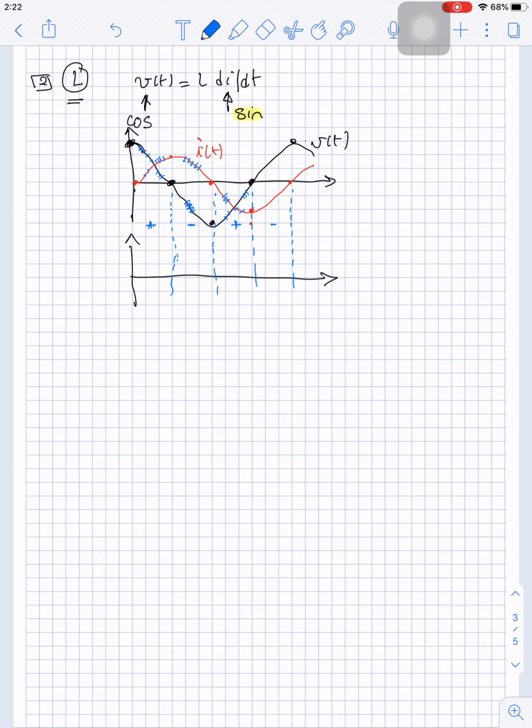That's why you can see all these parts are equal. So the wave is divided into 4 equal durations. That's why the shift is 90 degrees. Exactly 90 degrees. That's why the shift between V and I is exactly 90 degrees. So the average energy is 0. So the energy you charge equals the energy you discharge. This is what is called pure inductance or ideal inductance.